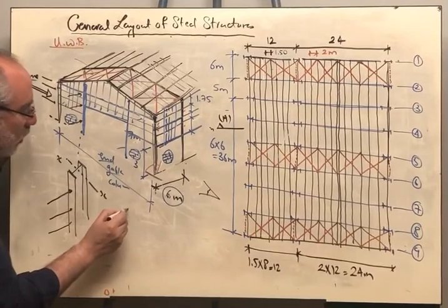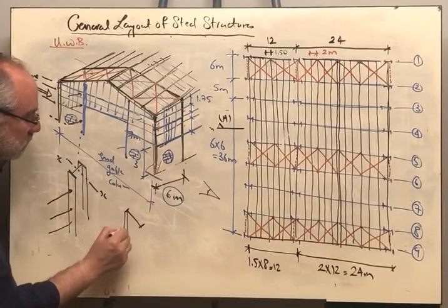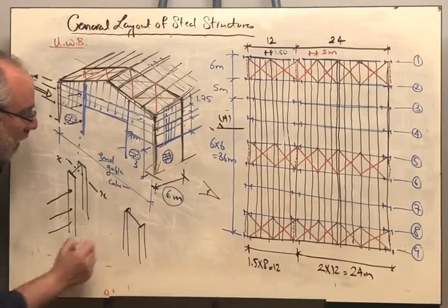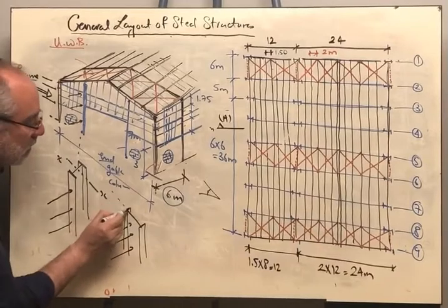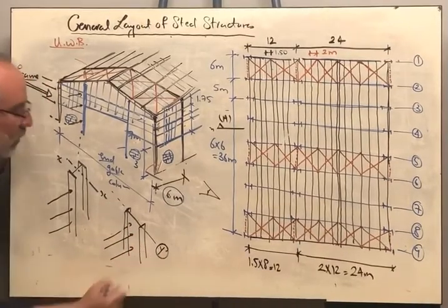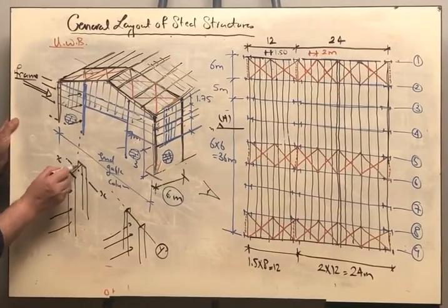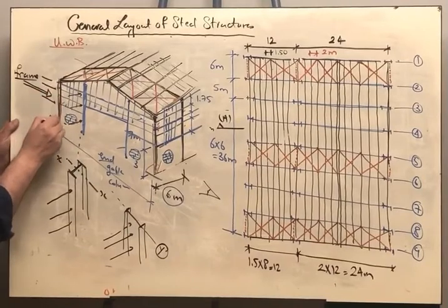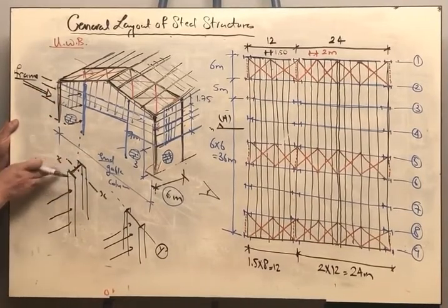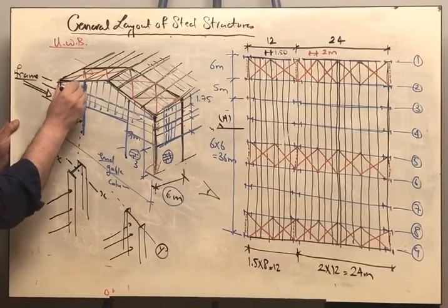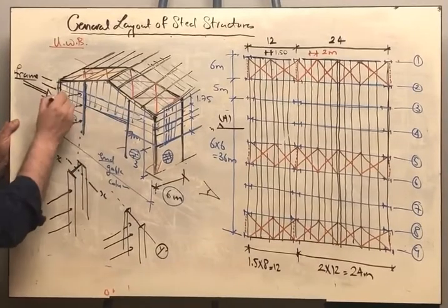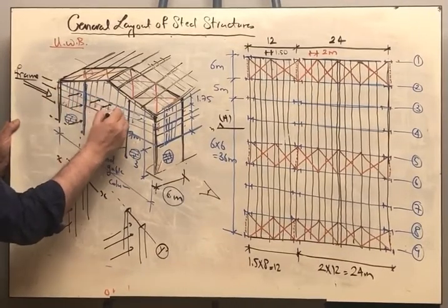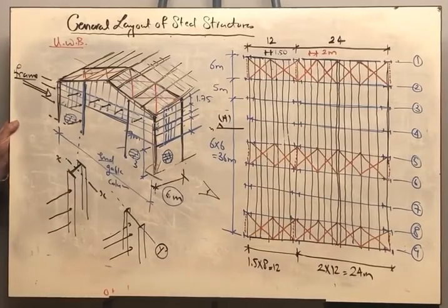But if you located the end gable column in this direction, and the wind is blowing perpendicular to the plane of the frame, then you are causing moment about the weaker y-axis. The end gable columns, especially, are rotated. They are not in the same direction as the columns of the frame, they are facing the wind, because the function of this column is to support the cladding and also to resist the applied wind loads perpendicular to the facade.